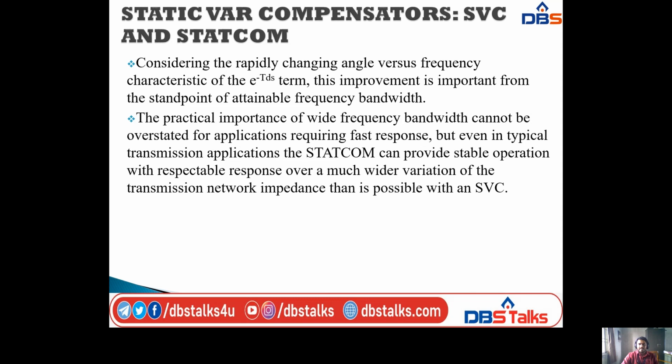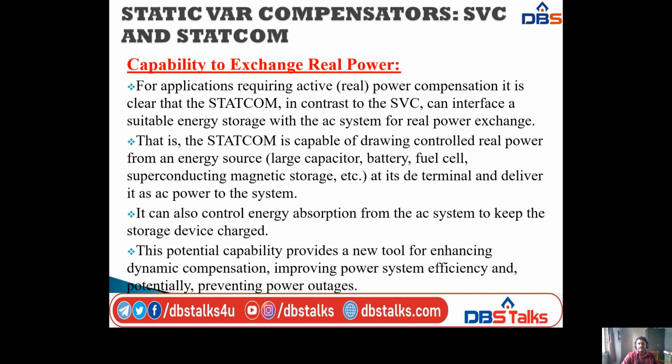Next comparison, that is capability to exchange real power. This is the fourth comparison between SVC and STATCOM. For applications requiring active, that is real power compensation, it is clear that the STATCOM, in contrast to the SVC, can interface a suitable energy storage with the AC system for real power exchange.